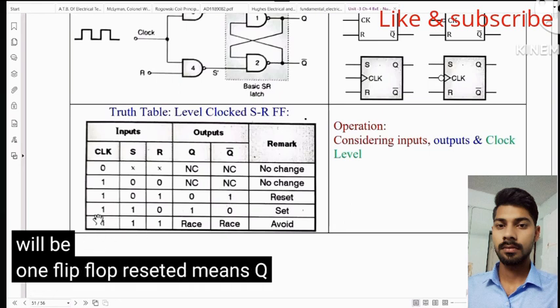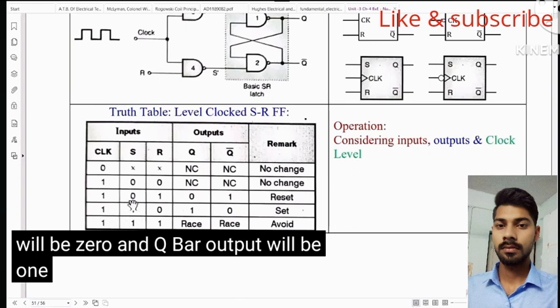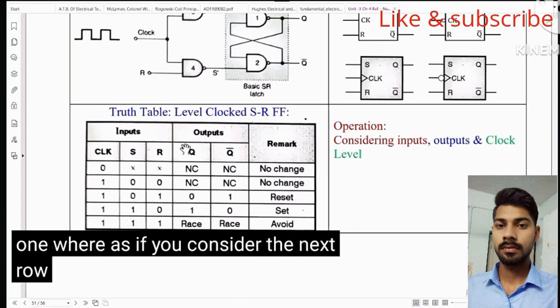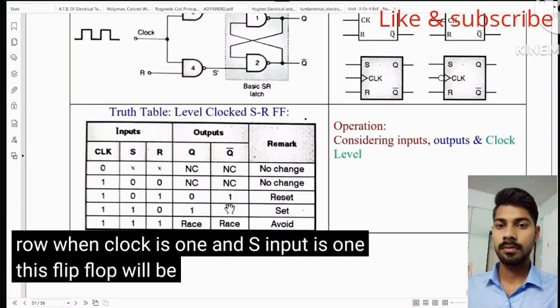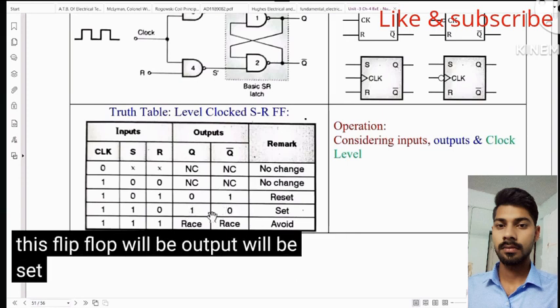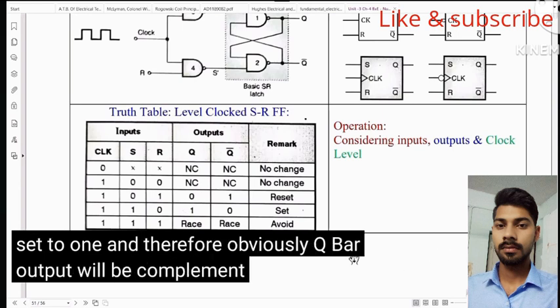Flip-flop reset means Q output will be 0 and Q bar output will be 1. Whereas if you consider the next row, when clock is 1 and S input is 1, this flip-flop output will be set to 1. And therefore, obviously Q bar output will be the complement of Q, that is 0.